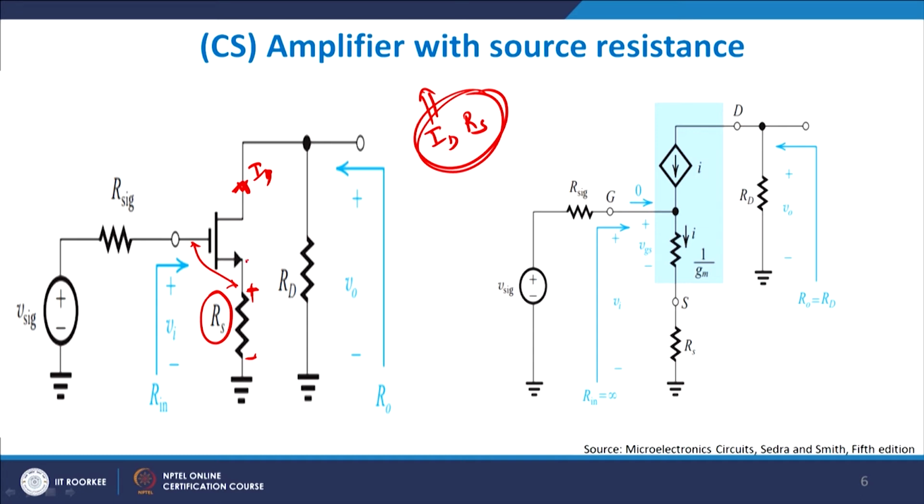So this is basically N and this is basically P, you have an N region here, and since on the N side you are giving a positive bias, you are reverse biasing it. Once you are reverse biasing it, your current is falling down. So whatever current increase you got by virtue of some problem, you will be able to reduce it by doing a negative feedback, right. So this is also the negative feedback.